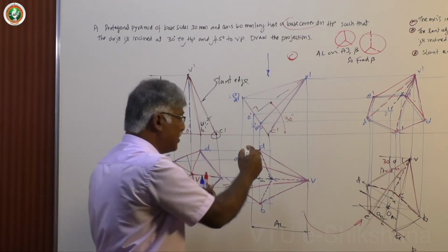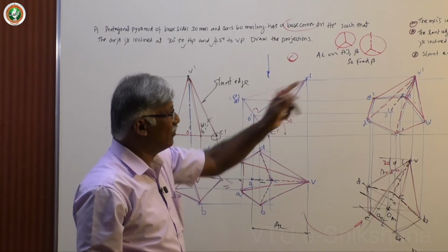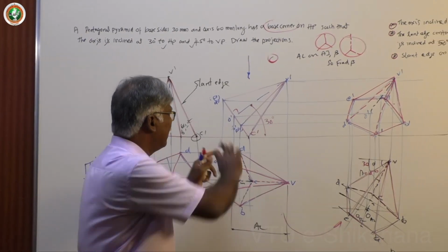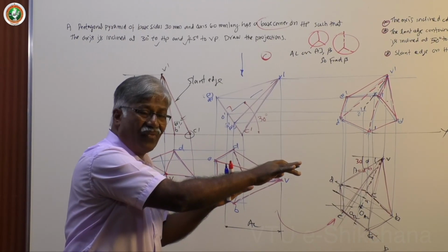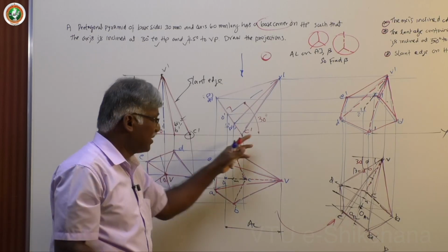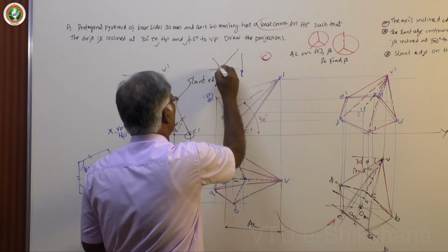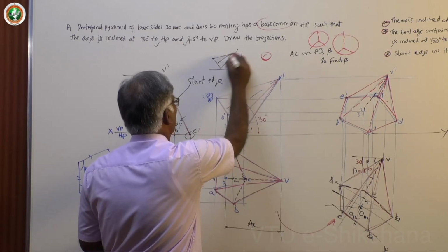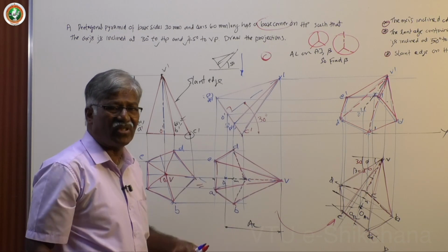For that, what you do is draw a line initially at 50 degrees, or whatever is given; I have given 50 degrees. Then rotate and see that this line is on that particular 50 degree line, that is all. Then do not worry about the axis. Here, the axis I had mentioned, in the slant axis, slant edge method, you mark this as 50 degrees. So again this type of problem you can solve. The rest of the procedure is the same.